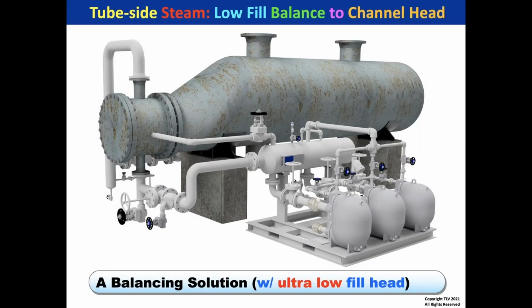Here's another interesting one. We like to see this outlet flange, ideally 80 inches high, but this was a really low one. So what we had to do is put a loop down here and design into the reservoir. We had to extend the reservoir, and we had to come into the center of the reservoir. So it was longer, and we came into the center rather than near the top in order to fill into the pump traps. We're paying attention to that water level line to keep it below the tube bundle in the reboiler. We don't really want to flood those tube bundles.